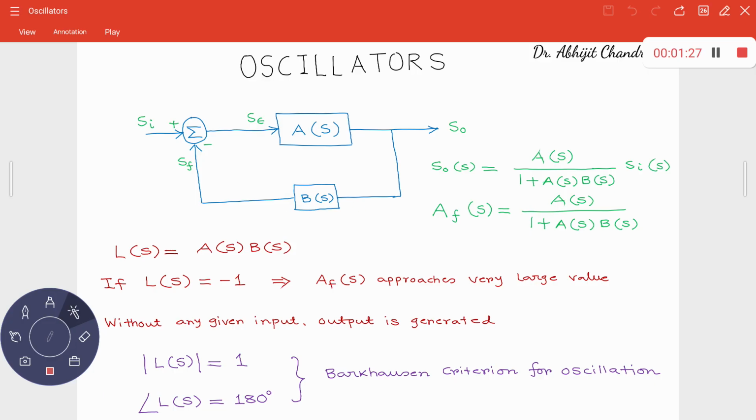Therefore, we expected the amplifier to provide the same gain irrespective of frequency. Sometimes the capacitor acted as a short circuit, as with a coupling capacitor, and sometimes as an open circuit, as with a bypass capacitor. Effectively, the impact of the capacitor was not seen in the amplifier design.